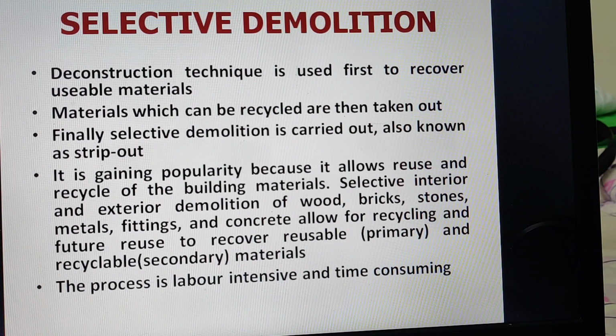Selective interior and exterior demolition of wood, bricks, stone, metals, fittings, concrete and other materials. Whatever usable materials are there, they allow for recycling and future reuse. The reusable materials recovered are called primary materials, and recyclable materials are called secondary materials.